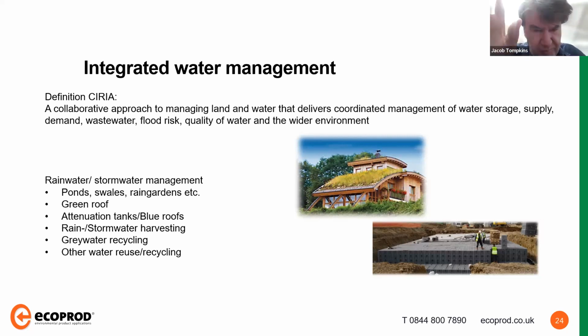The other option, if you don't have a big out-of-town factory, is to put in a green roof or a green wall. We're starting to see those in cities a lot. They have several advantages: the drainage advantage, the reduction of flooding, and the reduction in what we call urban heat islands, where cities often get hotter than the surrounding countryside in summer. Also, they're really good to look at. They make your buildings stand out. They're good for biodiversity, and again, we've got loads of examples of this. They're not that difficult to do, but it's worth bearing in mind that you can't do both rainwater harvesting and green roofs at the same time. So you just have to think of the wider picture when you do this.